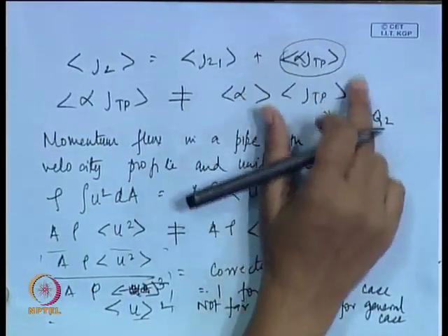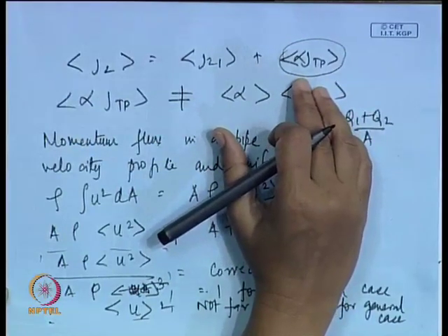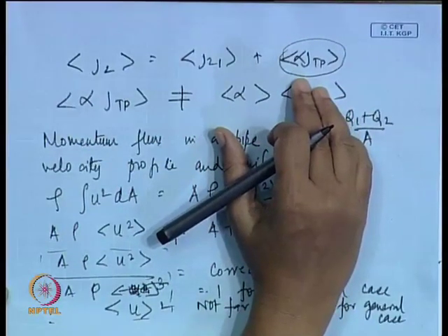This creates a problem. Now, this is a product of two quantities which might vary across the cross section. So, what has to be done? The volumetric concentration has to be measured at each and every point, your overall volumetric flux has to be measured at each and every point, then the product has to be made and then it has to be integrated. For engineering applications, this is very, very difficult.